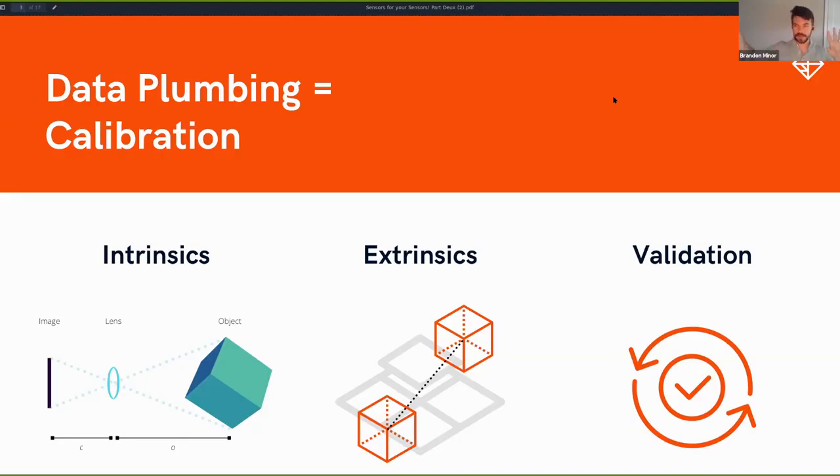We need to know the extrinsics, which is its relation to other sensors on the machine. Extrinsics can be spatial. You can have 2 sensors at a distance, and you need to know how to register them, but it could also be temporal, right? You have connections between these sensors, and you need to know exactly how they differ in time so that you can better judge their performance.